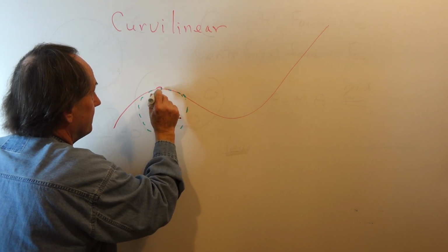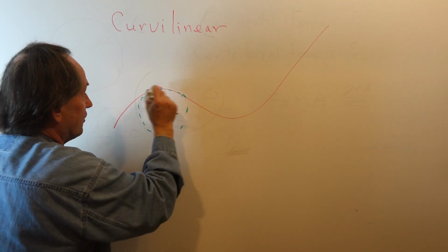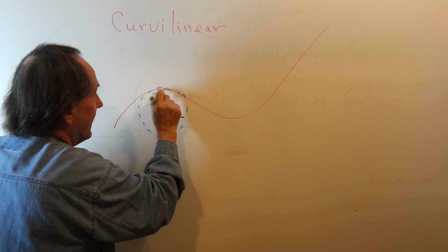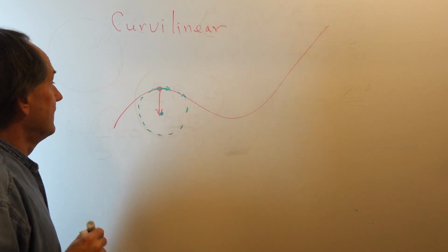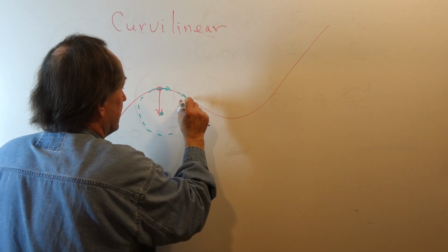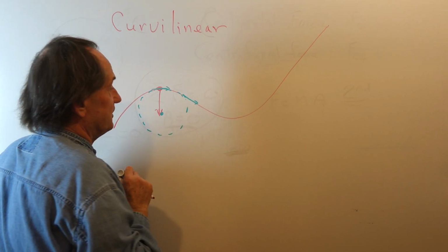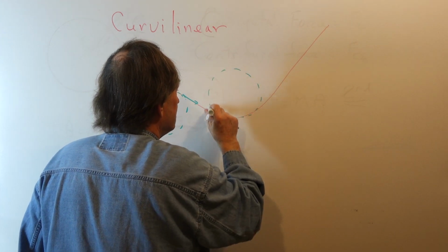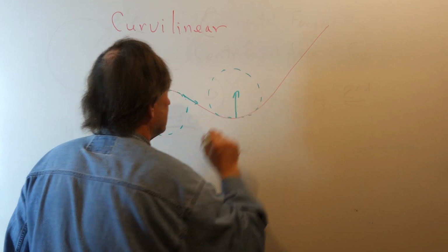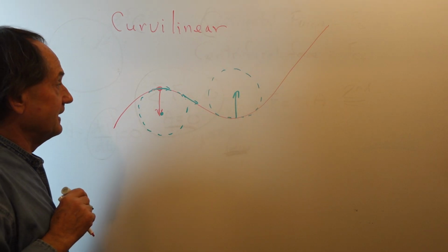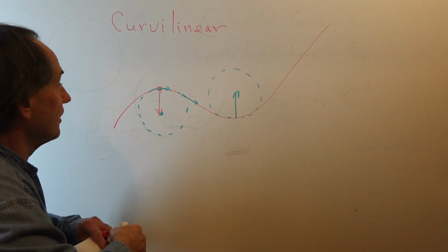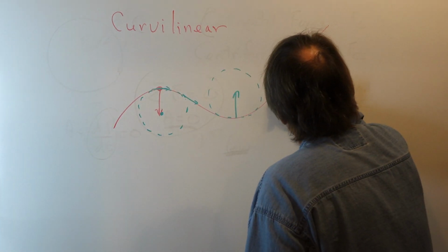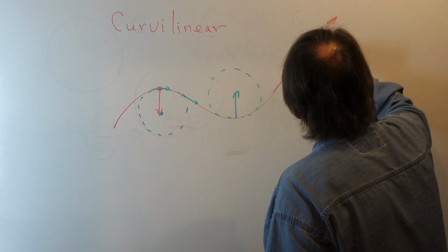At this point, a circle of a given radius can describe the motion as this object is passing by. Say in this part where it's straightening out, we have pure translation, and then over here we have again some more rotational motion, and we have a centripetal acceleration directed towards the center of curvature. And then if we go out further, the object can just have pure translation going in a straight line.